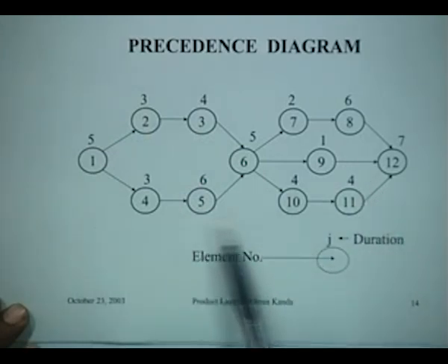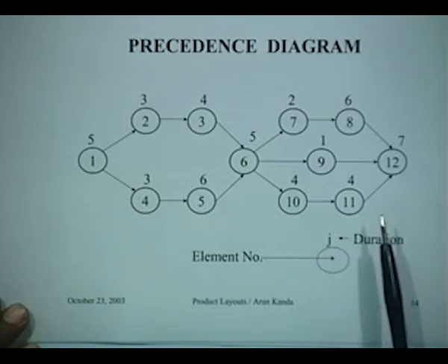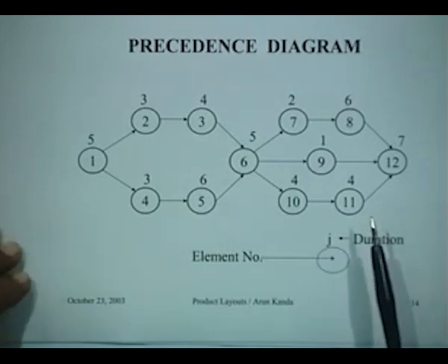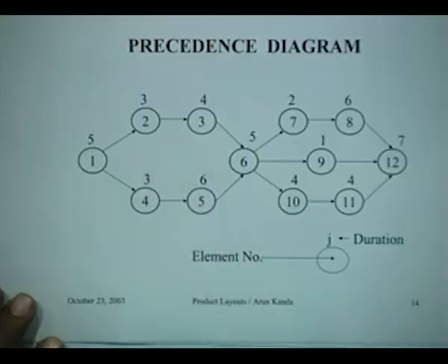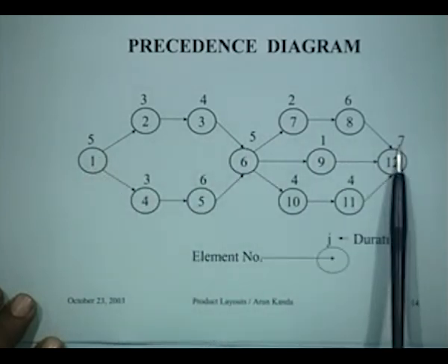So from this we would like to possibly design an assembly line. Let's see how we can design an assembly line manually for this operation, and then we'll compare it by using the ranked positional weight technique. Now clearly in this particular case we are going to group these operations. One thing is clear: what is the maximum time that is required for any operation? That is 7.